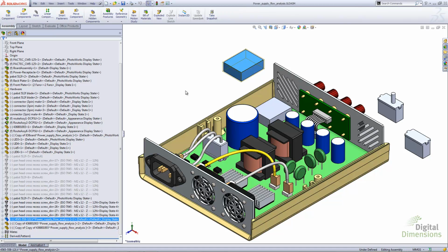And ever since 2010 and later, we cannot change that functionality. So by default, it had part 1, caret, then assembly name. If I wanted to simply rename this to just plain part 1, that is not a possibility starting from 2010 and later, due to changes done internally to the SolidWorks software.